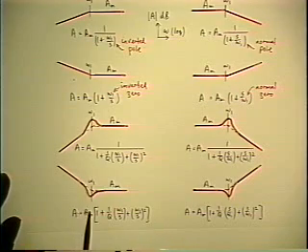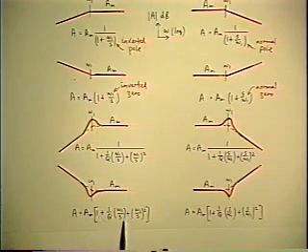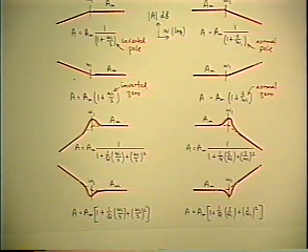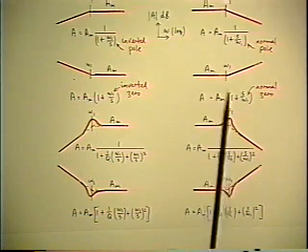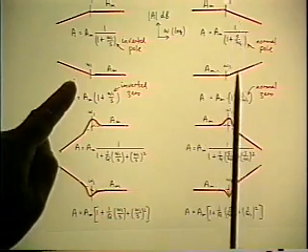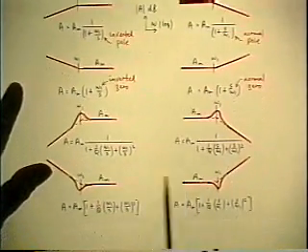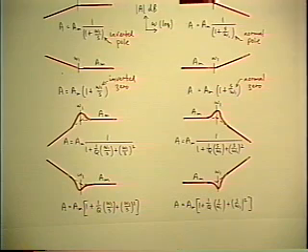And the same if you make a vertical inversion of that. Now you have a pair of inverted zeros, either real or complex. So we have the full symmetry now, both for single poles and zeros and for double poles and zeros. Okay, all of that has come out of the voltage transfer function of the RLC network, and the next thing we'll go on to is the input and output impedances.